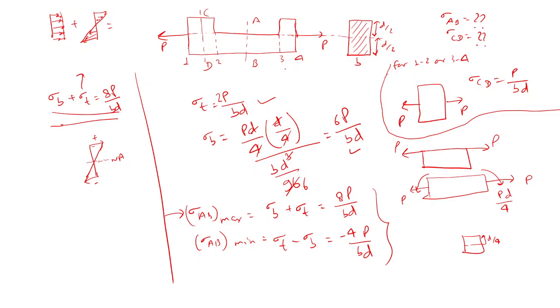And now coming to the mid part, the loading condition is like this, right? Yes, sir. So now we shifted the load to the center. When we shift the load to the center, a moment will come, because of the shifting of the load. So when we shift the load from here to here, how much moment will come? P into this distance. How much is this distance? Because this is D by 2.